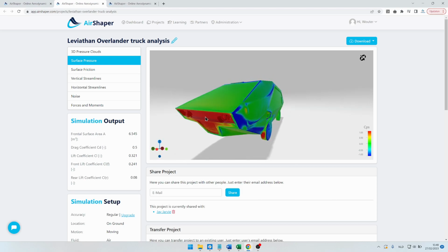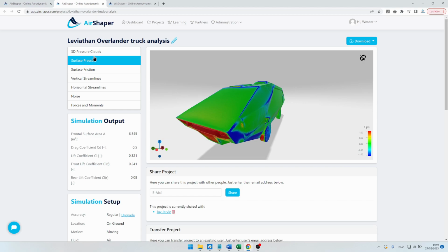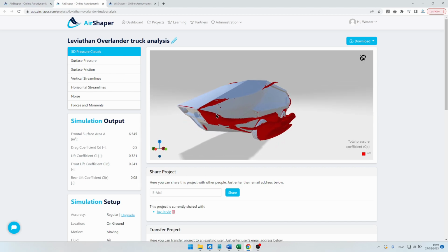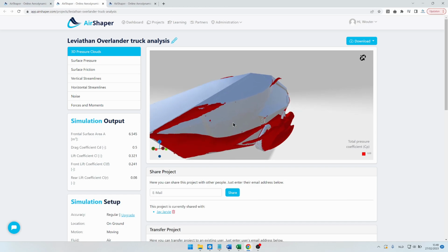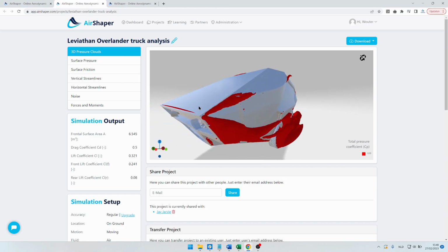And when it goes via the sides, there's this very sharp edge here. And this is way too sharp a corner for the air to stay attached. So it separates and then reattaches further downstream. But in the process, it actually creates a lot of flow separation. A lot of vortices are originating from this point. So the air pushes upward, then tumbles down the side. And this creates a swirl as it goes via the side, and an opposite swirl on this side.